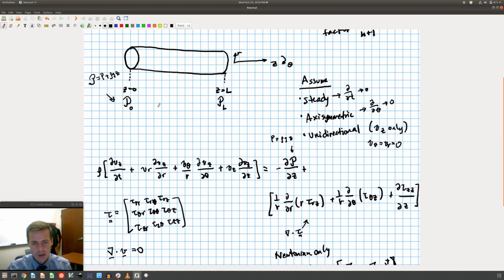I also wanted us to recall briefly that we talked about non-Newtonian flow, and we drew little axes with the viscous stress, or the shear stress, versus the shear rate. I said Newtonian was a straight line, and power law went above or below it, and I wrote this expression: tau equals m gamma-dot to the n. So the shear stress was equal to some constant m times the shear rate to the n. Now we've been a little more sophisticated about shear stresses and shear rates in this part. We've been using viscous stress tensors instead of just simple shear stresses, and rate of strain tensors instead of simple shear rates.